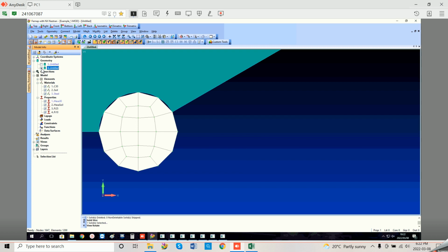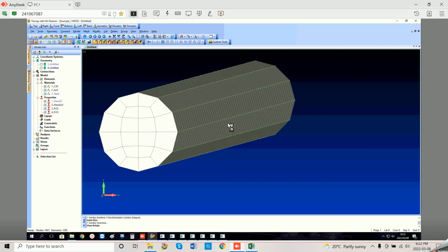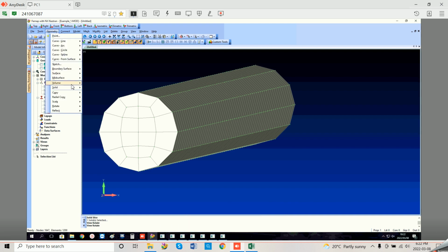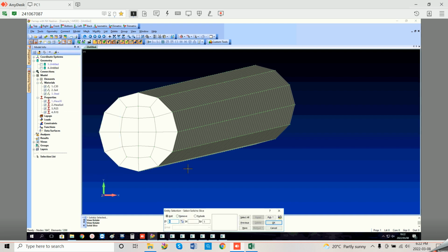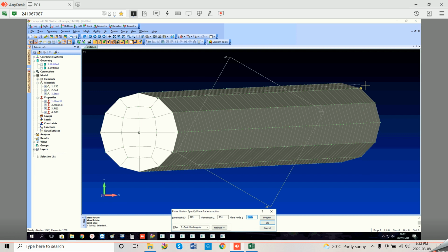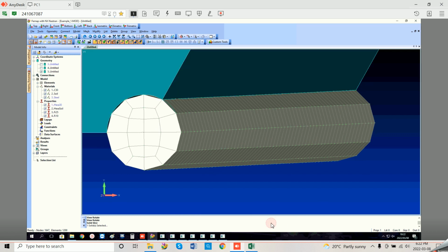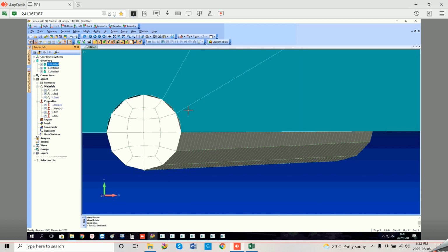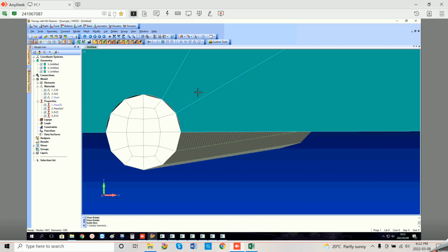So now we're going to do the same thing with this one. So we're going to go, okay, geometry, solid, slice, number 4, because 4 was that geometry there. And now we're going to select this node, your center node, and that node. Boom, done. Okay, so now you can see we have 2 slices, so we have one more slice to do.